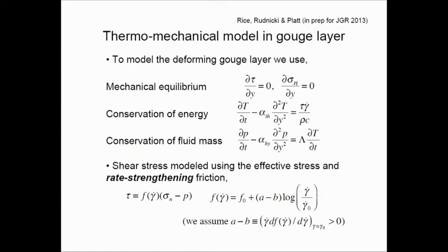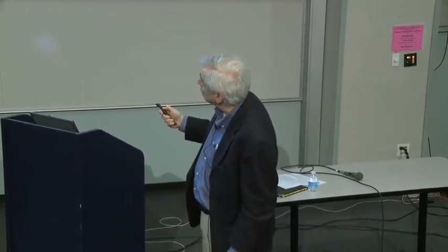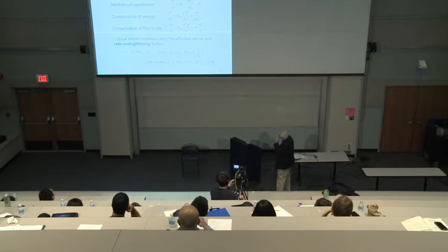We have an energy equation, which is in its simplest form as this. So this is the rate of temperature rise, which is a rate at which the material takes up internal energy. Why does it take up internal energy? Because it's being heated, but some of the heat flows away by heat conduction, which is the origin of this term here. The alpha thermal is the thermal diffusivity, I should say, typically of the order of a square millimeter a second.